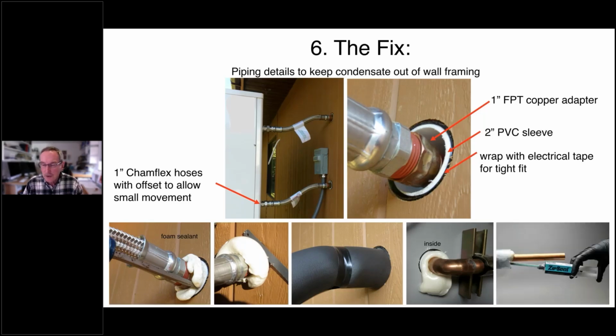And I just want to show you, here's another product that's on the market. This is a 2-component urethane. When you push that syringe, you're basically mixing a hardener with the polyurethane. And if you have an especially deep cavity, that ensures that that material is going to cure into a solid all the way through there.